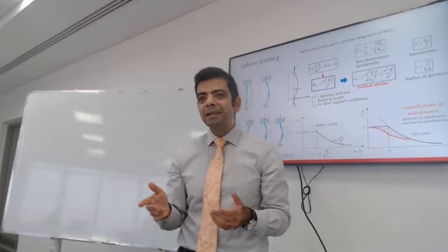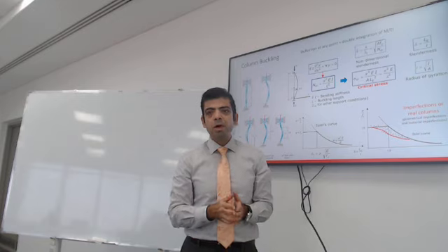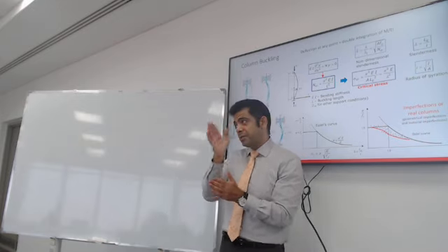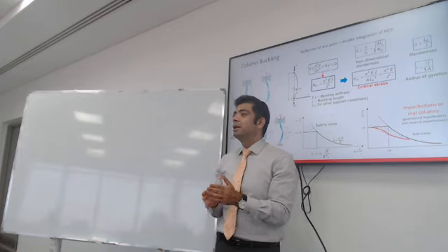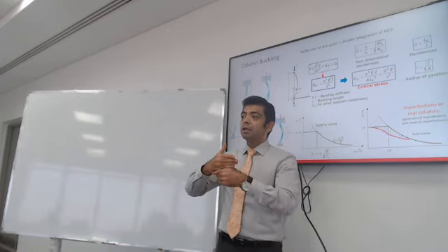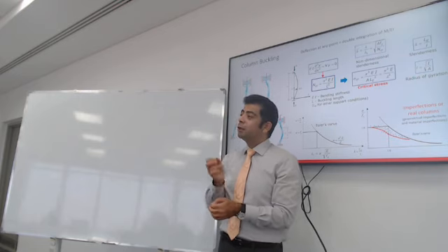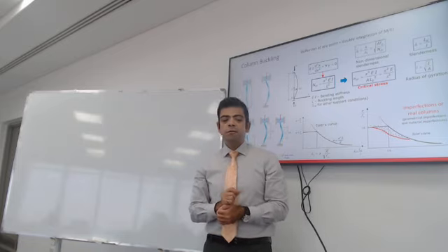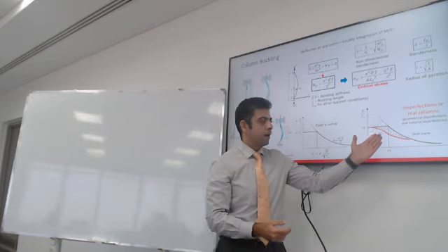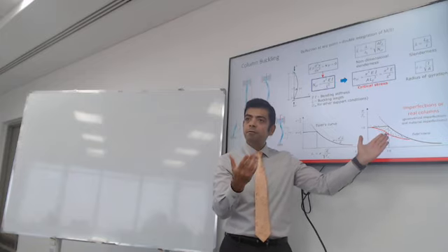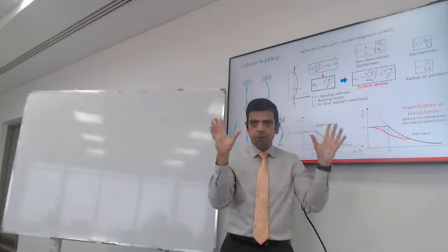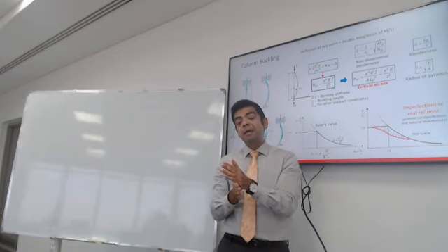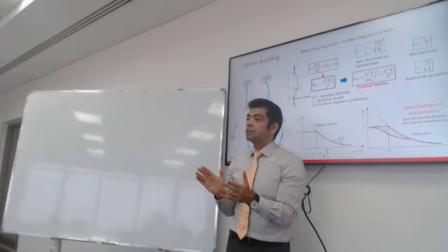That's exactly it. It's called the imperfection factor. Because the column that comes out of the factory is not 100%, 99.9% straight. You could have a dent. When you load it, you're not loading it perfectly in the center. It could be a millimeter off, within certain tolerances. So actual life is different from theoretical, perfect circumstances where the load is perfectly in the center, the column is perfectly straight, and there are no imperfections whatsoever.